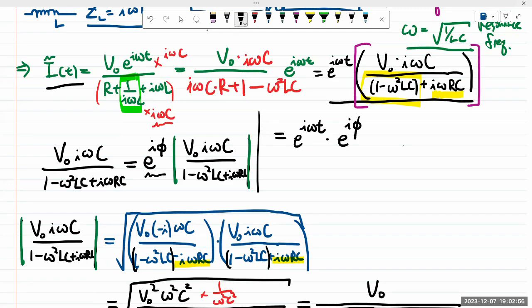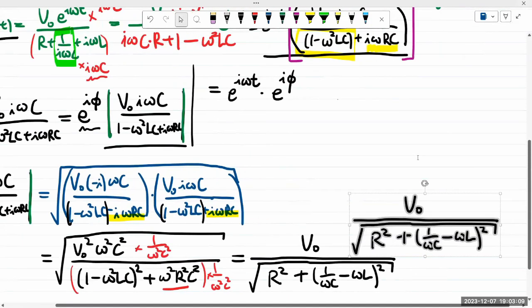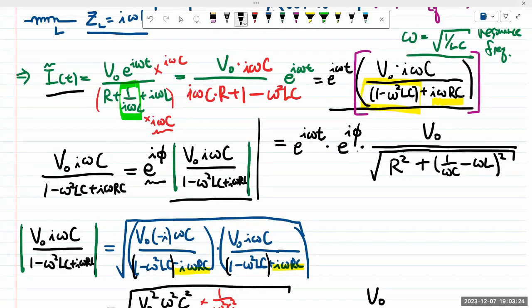And then for the quantity that determines the magnitude, we can now say, copying and pasting this, that this will give you the magnitude of the current. So if someone was asking a question like, what is the IRMS? Then I can say this top part is VRMS, or it'll be proportional to VRMS. I can write that in terms of VRMS by dividing it by this factor here.